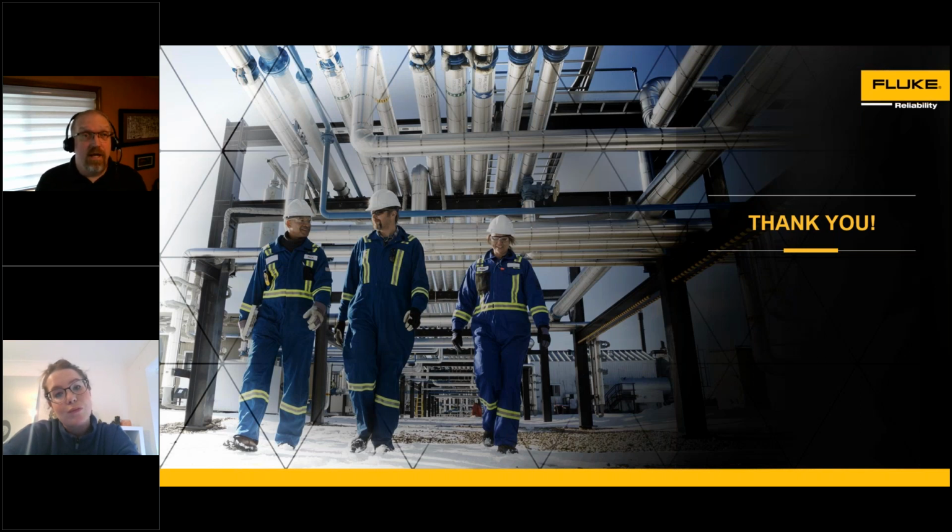What you do is, when you start your vibration analysis program, you collect data in what you believe to be a fault-free condition. We'll call that your baseline data. Once you've collected your baseline data, you can go through and set your alarms.